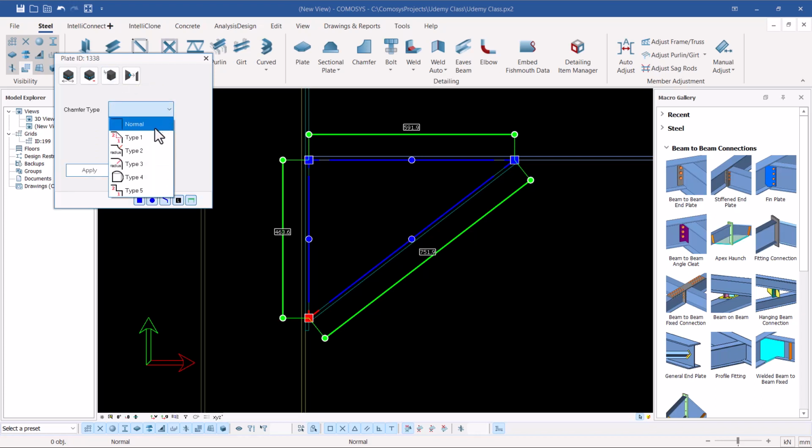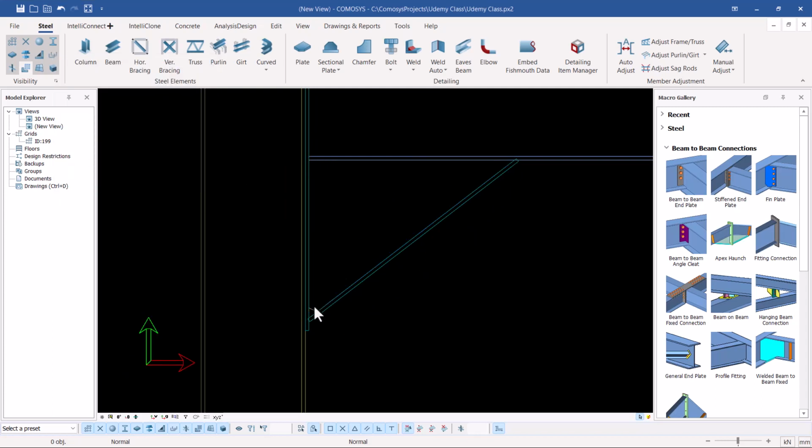And what chamfer do we want? You want that one, and maybe we can feed 30-30, that will be okay. 30-30 and click apply and give it an OK, and apply that and close. So we can always come here and apply the same thing here.